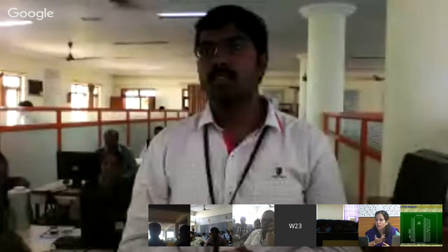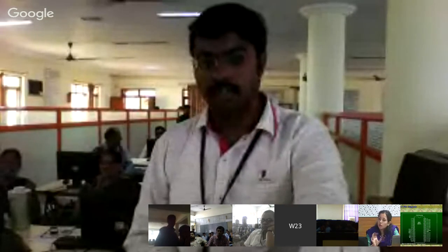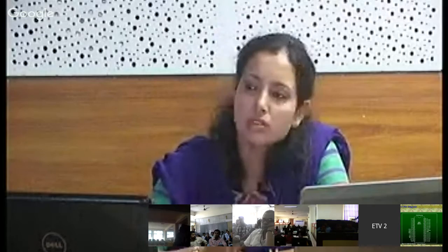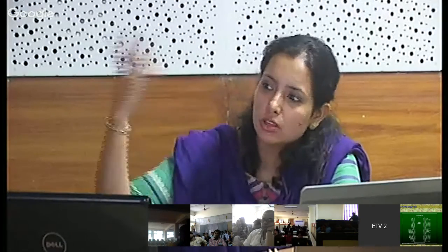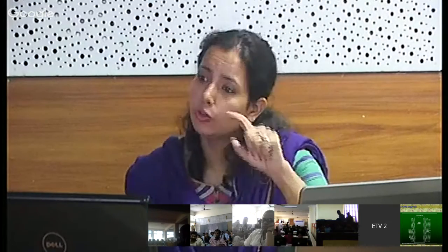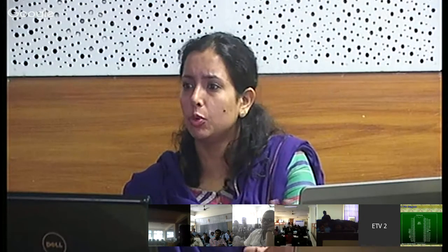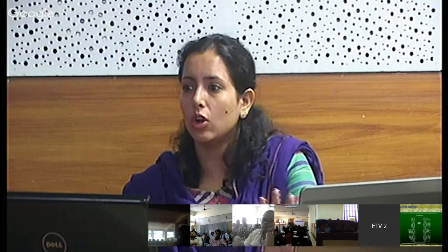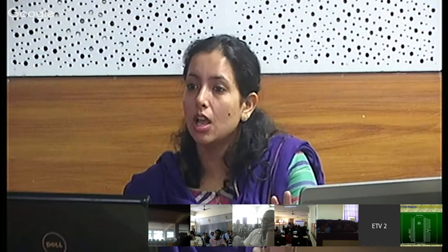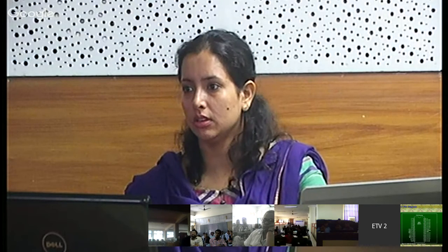5 volts. Naturally, it should be 5 volts because VCC is nothing but 5 volts. All the ports except port 0 have got those internal pull-up resistors which will connect them to VCC. But if you check the status of port 0, it will have something like 1.2, 1.3, because it does not have internal pull-up resistors. So if you are getting such status, that means your microcontroller is working fine.